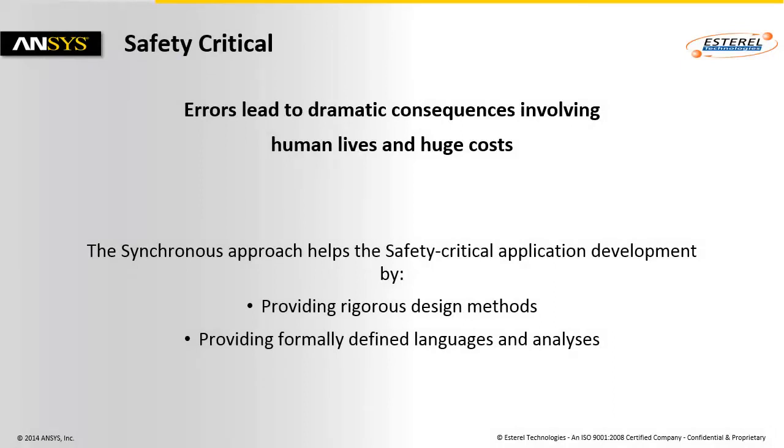A synchronous approach comes with rigorous design methods and enables formal verification. This is very important because, as I mentioned before, errors in reactive applications can have dramatic consequences involving human lives and huge costs. And special care must be taken while developing a safety-critical application. This means no infinite loops, no recursion, safe memory management, etc. To ease the development of such applications, one must take into account these constraints.